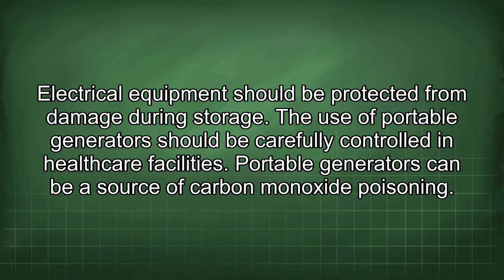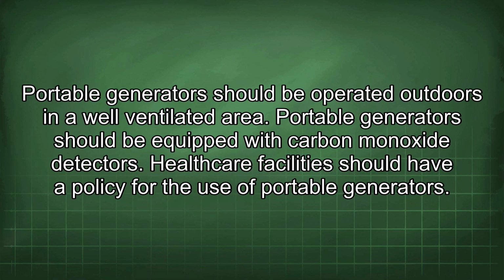The use of portable generators should be carefully controlled in healthcare facilities. Portable generators can be a source of carbon monoxide poisoning. Portable generators should be operated outdoors in a well-ventilated area. Portable generators should be equipped with carbon monoxide detectors.